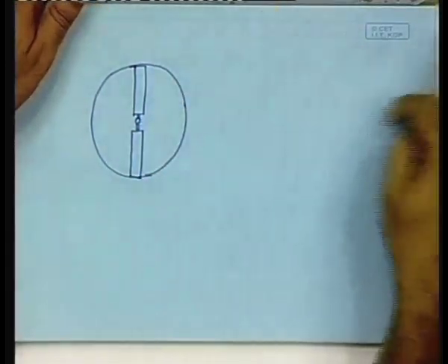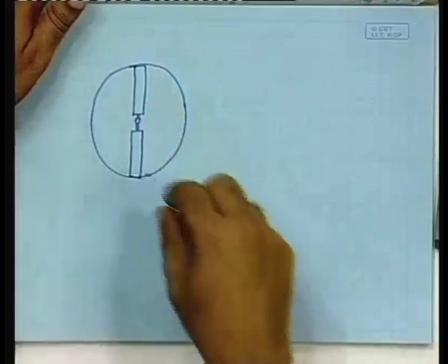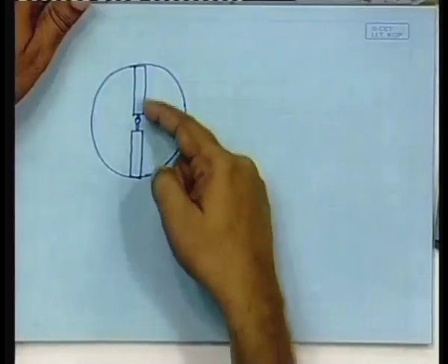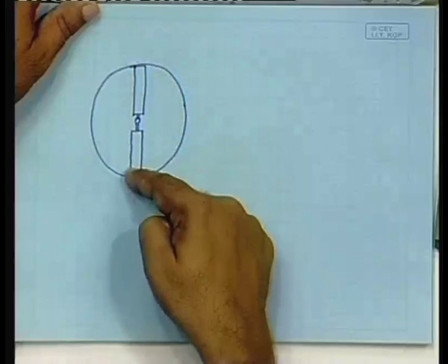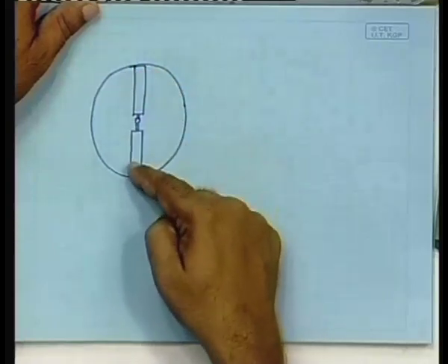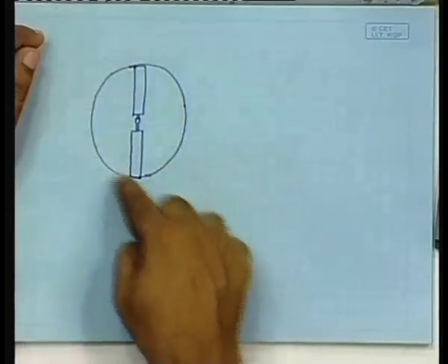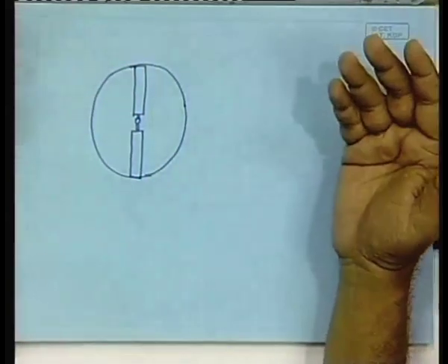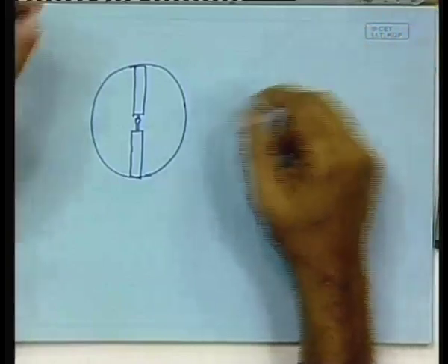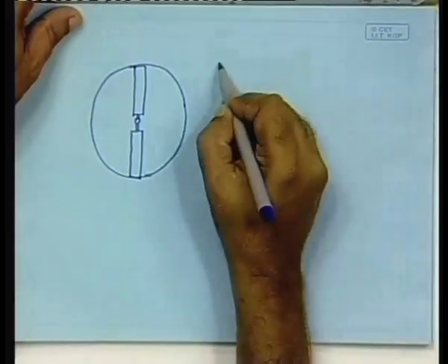Imagine that you have put a light here and you see the shadow. The shadow will only take the area of the actual blade that is seen by the light, divided by the whole swept area. That is known as the solidity. So, solidity is